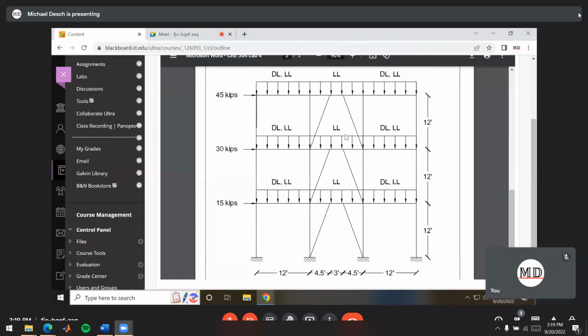So in this case, what we can do is free up some space architecturally in this bay by not having it go all the way across and basically block off that whole wall all the way up and down the building. So if you need to be able to get through here, that's a good solution for that. So it's a compromise you can make with the functional need of the building. Though a lot of the time they'll put braces somewhere in the core area, like behind the elevators or next to the stairs or way on the ends of the building. So it's not quite as much of a concern. But if you need a brace somewhere and you still need people getting through, this is a good one.